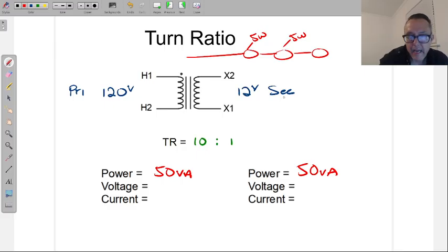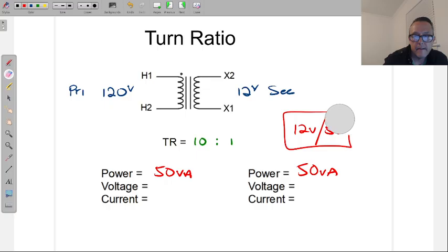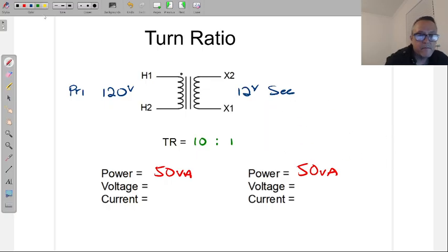All right, say for example the LED lights were 12 volts with 5 watts each. Using the voltage we have here for this transformer, we can get 10 of these lights on there. So now we have 2 bits of information to do Ohm's law. We know the primary side voltage. We know the secondary side voltage. And now we can get to the amperage.